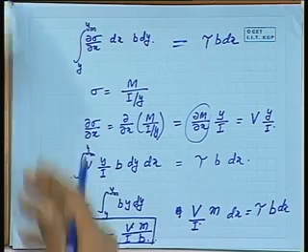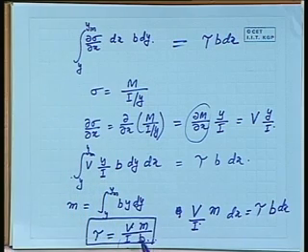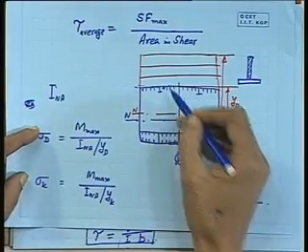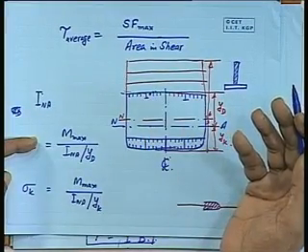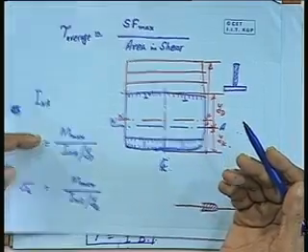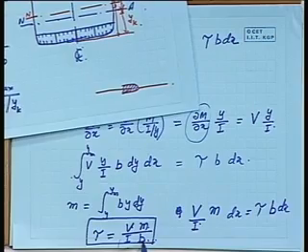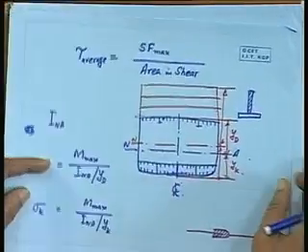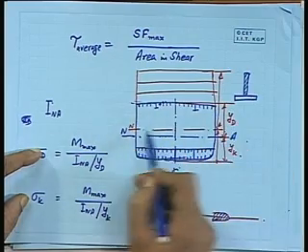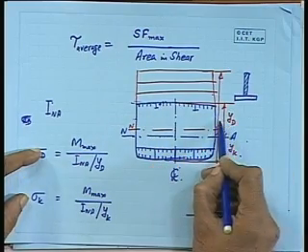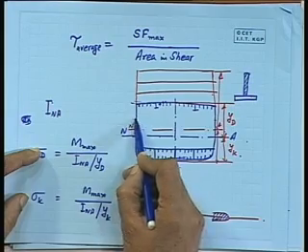Right. So this will be maximum at this level, at the neutral axis. If you integrate from here to here, then only it will be maximum. If you integrate from here to here, it is 0. If you take the value at the deck itself, then it is 0. Then divided by b, b is the width of the cross section. Now what happens? If you take the deck, this is the cross section. If you take the sides, then this is the cross section plus this is the thickness. b is only the contribution from this.